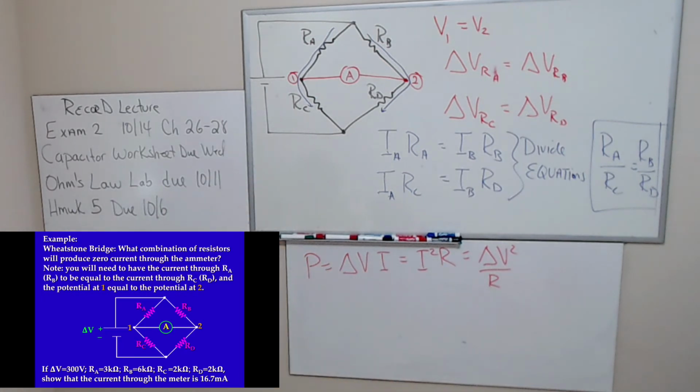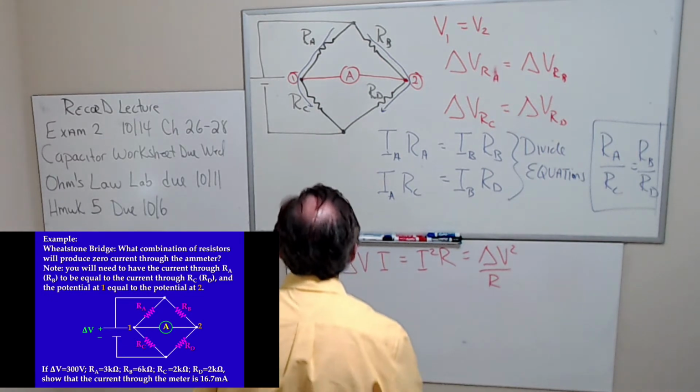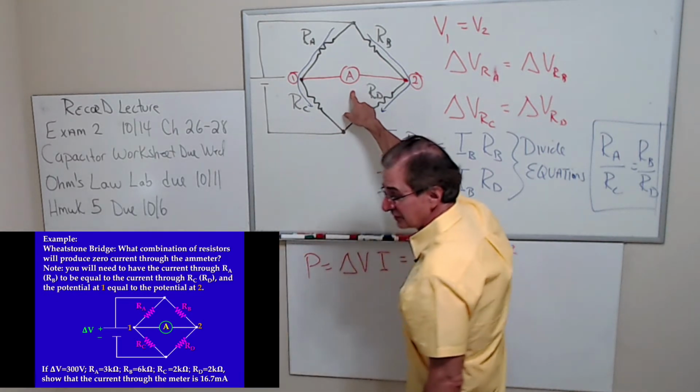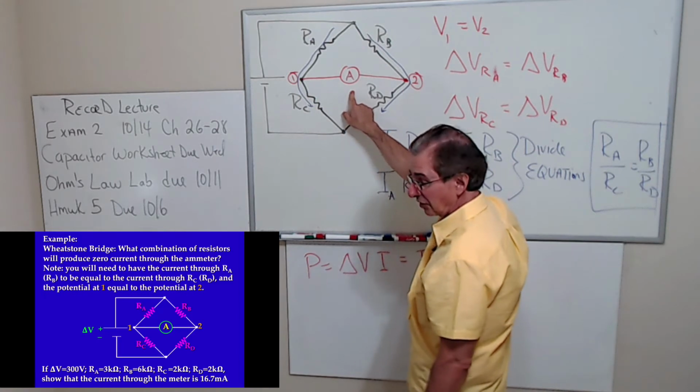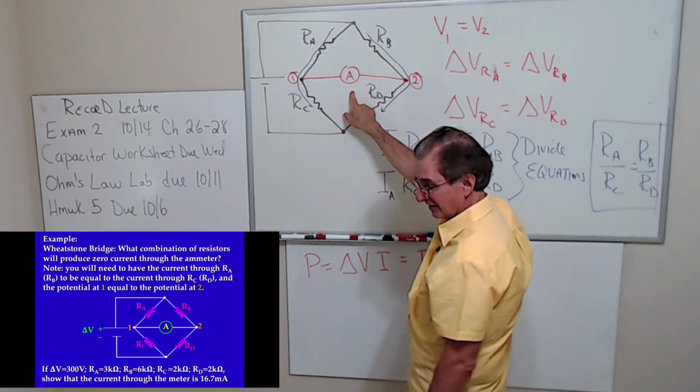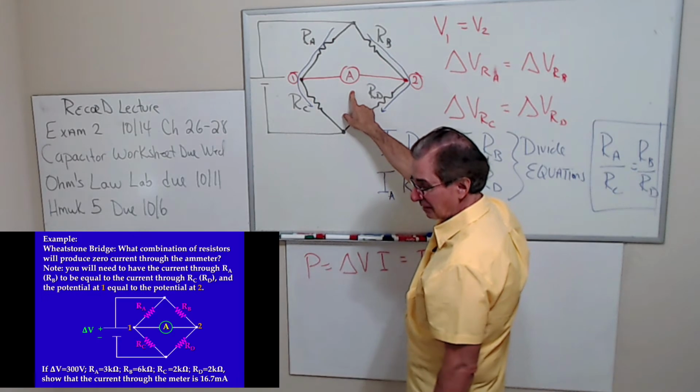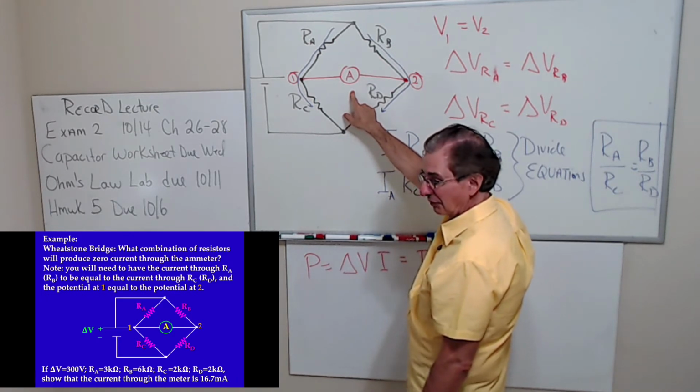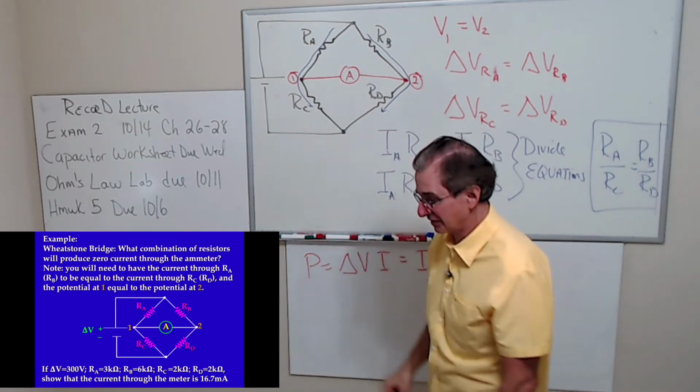For a long time. And in fact, I remember I taught a lab at Sac State, and they might still do that lab. They have a very sensitive version of this for measuring low resistors. The only problem with your ammeter is you got to make sure it has a very low resistance. When you set the ammeter for really low current, its resistance increases.